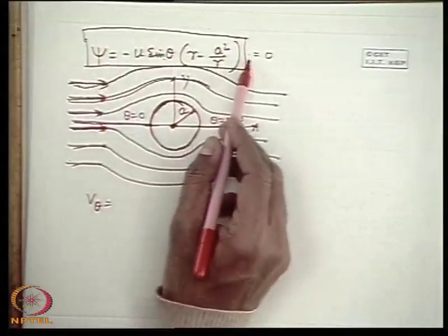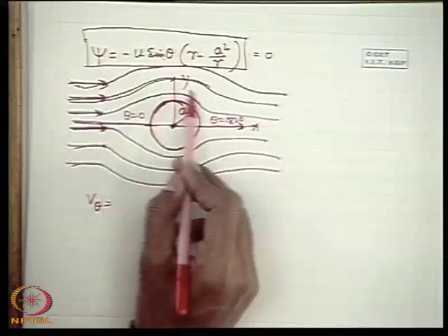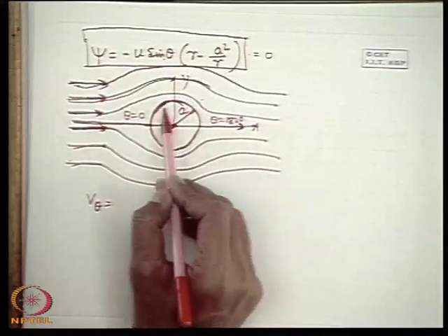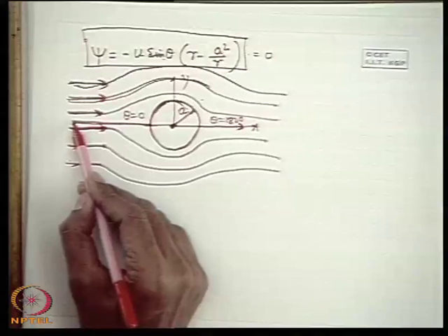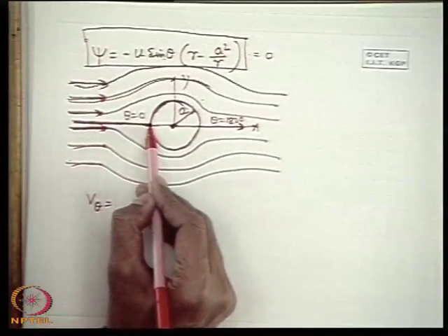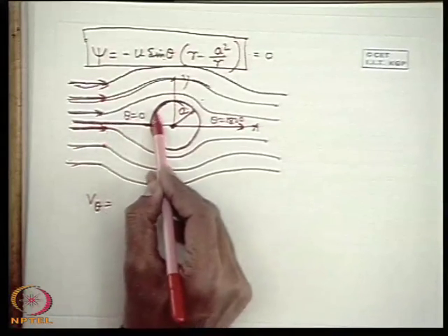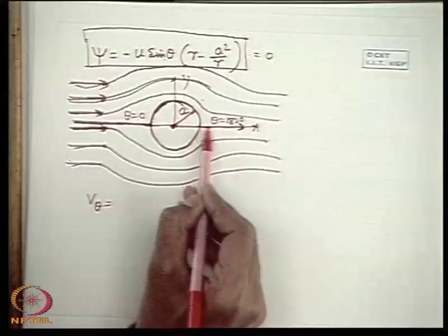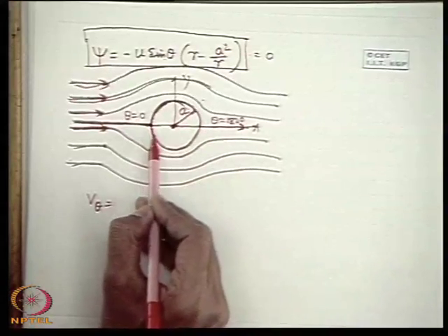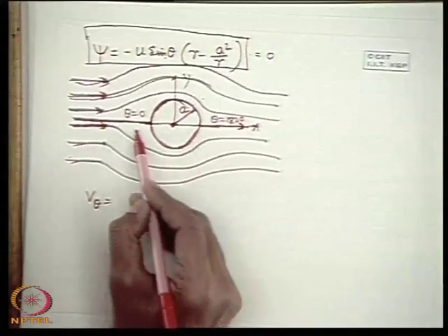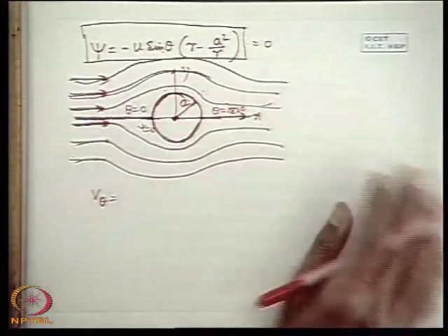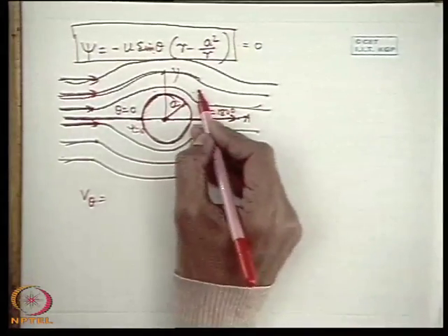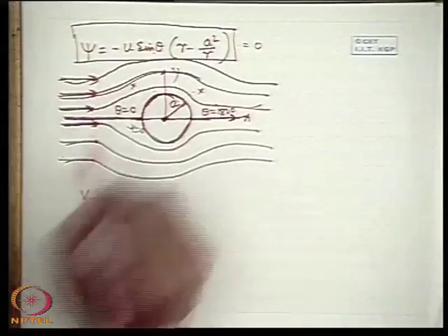So this is the stream function for a parallel flow of ideal fluids past a circular cylinder whose radius is a. So therefore, the fluid particle following this line, theta equal to 0, along the cylinder and then going via this line, and another is diverted in this way, this corresponds to psi equal to 0. These are the lines corresponding to other values of psi. Let us find out the V theta and Vr at any point here or any point here.